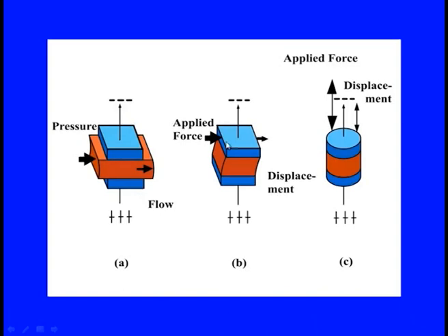With the shear mode, as the name suggests, the plates are parallel to each other, either in rotation or otherwise, and we have the shear force. And third, with the squeeze part, the displacement changes the distance, and because of that the squeezing occurs on the magnetic particles, and through that high force with low amplitude applications can occur.